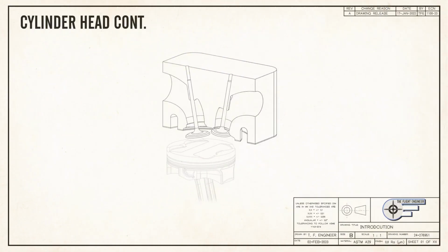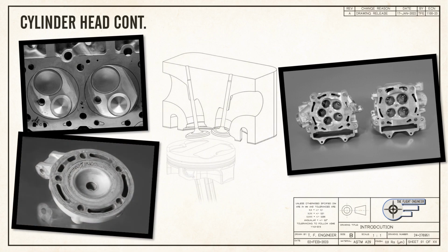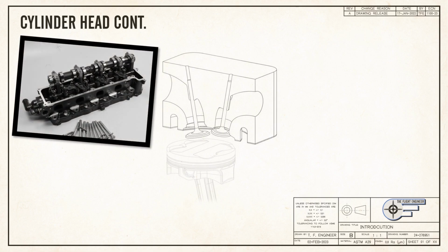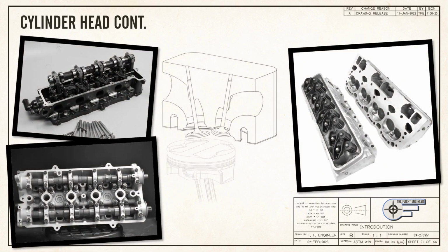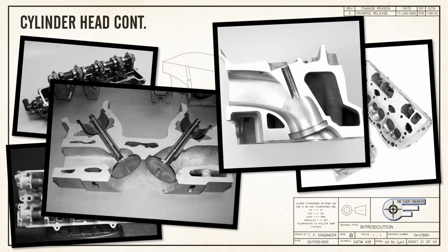Cylinder heads, like blocks, also come in a dizzying array of variation. 2 valves per cylinder, 4 or 5 valves, no valves, no problem if you're a 2-stroke. You can have 1 camshaft, 2 cams, or no cams at all. All these are common. Additionally, combustion chamber shape and port design are critically important to performance and efficiency. They have to be carefully matched to the engine's other characteristics, so no 2 designs end up the same. As with the block, the wide variability is driven by the designer and the demands of the application.